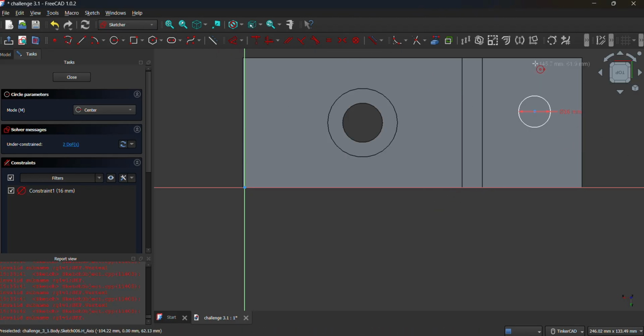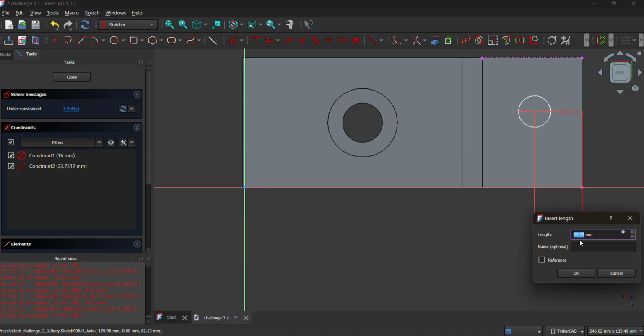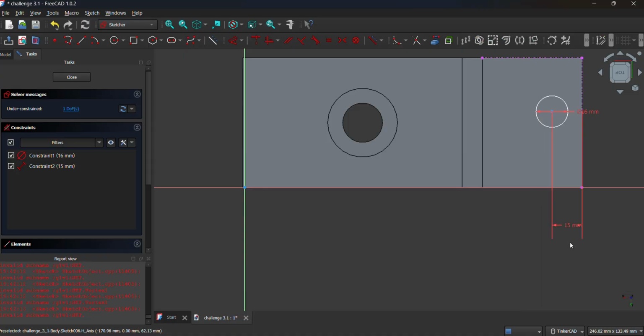So let's try first if the sides or the edges are clickable. Okay, the edges are not clickable, so let's create an external geometry. Then click dimension, click the center, and then the external geometry. Again, in order for you to know that the correct edge is clicked, the purple broken line turns gray. Okay, so that is 15 millimeters according to the reference.